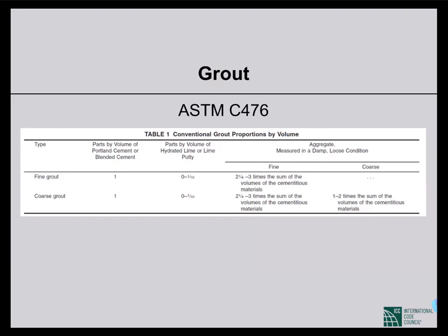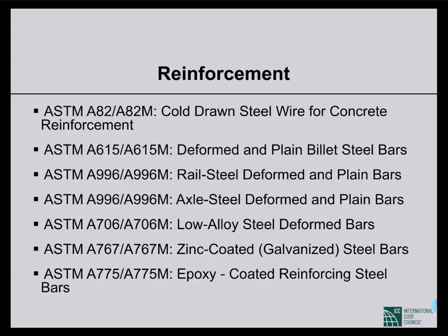We have to classify the grout because this is important when we decide about the clear spacing between the bar, rod, and masonry unit. For fine grout, we can allow less spacing. And for coarse grout, we have to leave greater spacing. So for that, we need to know what type of grout we are going to use.